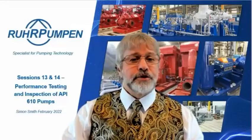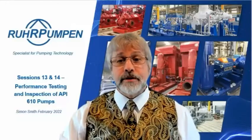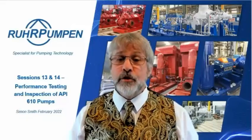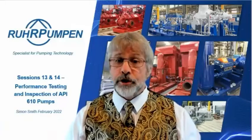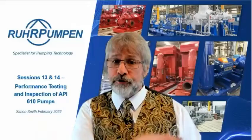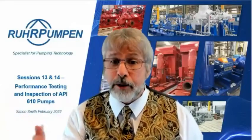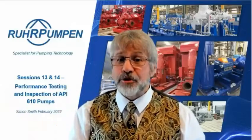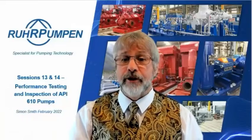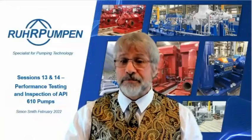Thank you for this one, Shyam Kumar. What's the criteria for successful complete unit test? That's something that you need to define when you specify the complete unit test. What are you going to be testing? Are you going to be doing a complete flow against head, or are you just going to set it at a set running point, maybe minimum continuous flow, maybe actual point? You have to define all this in your discussions before carrying out the complete unit test. And what are the acceptance criteria? Perfectly correct.